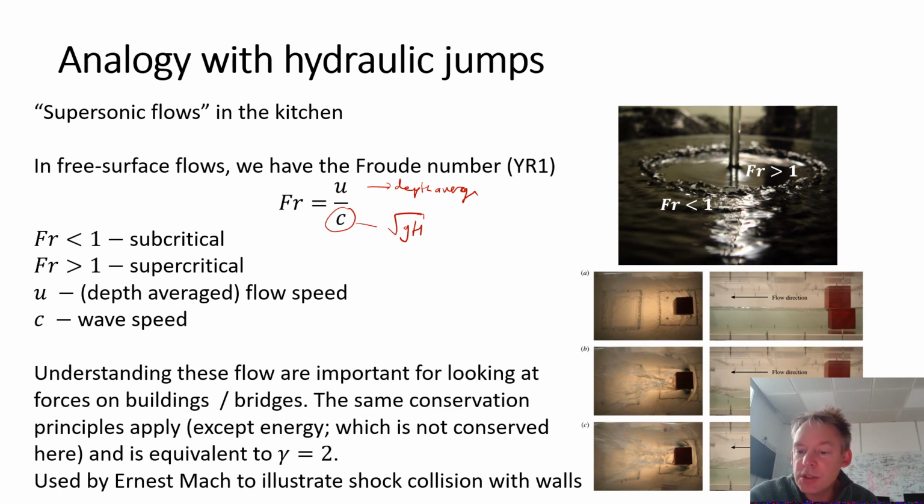So you can apply conservation of energy, well, energy doesn't work so well, conservation of momentum, conservation of mass in this particular case. The change in specific energy is actually used to look at dissipation. Dissipation is important in weirs because that's how you reduce the momentum of your stream. If it's too fast, it'll start eroding the ground.